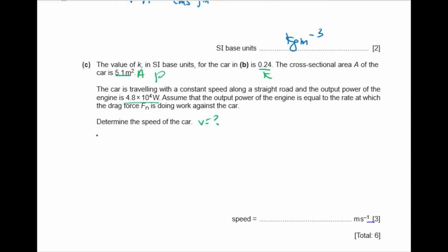So formula, power equals Fv. Force just now is v squared A k, so power equals v cubed A k. So power is given as 4.8 × 10^4.